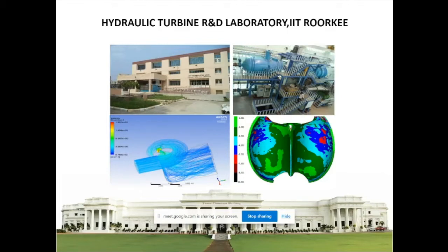So nowadays people are going for CFD analysis so that they can bypass the model testing at some level. And the second advantage of using CFD in the hydro turbine is that we can simulate n number of models, n number of cases, which is not possible if we follow only the model test.